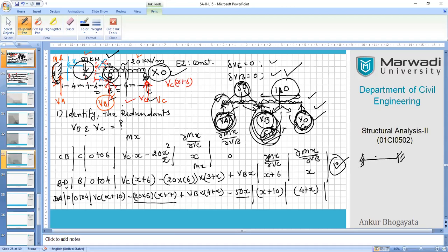In this case, what we used to do, we used to calculate end moments and the span moments, right? Like this. So you cannot avoid span moments in this case. So definitely we will be receiving some span moments at point D and the middle point, or somewhere where the point of contraflexure takes place in this structure. So in total, it was a good try, Darsha.